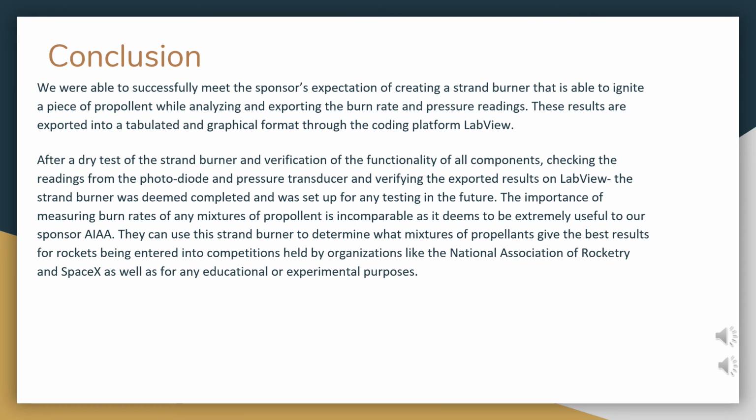We are able to successfully meet the sponsor's expectation of creating a strand burner that is able to ignite a piece of propellant while analyzing and exporting the burn rate and pressure readings. These readings are exported into a tabulated and graphical format through the coding platform LabVIEW. After a dry test of the strand burner and verification of the functionality of all components, checking the readings from the photodiode and pressure transducer, and verifying the exported results on the LabVIEW, the strand burner was deemed completed and was set up for any testing in the future.